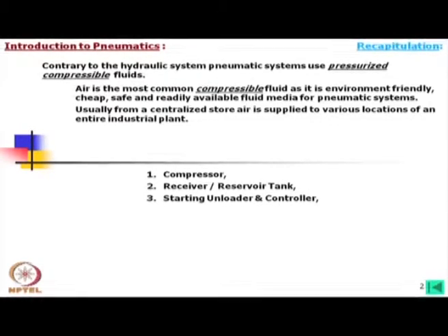Then, the compressor, as you know, cannot run continuously, and it is not desired that it would run continuously. There is a system by which the compressor is stopped when the compressed stored air reaches a certain upper level of pressure.